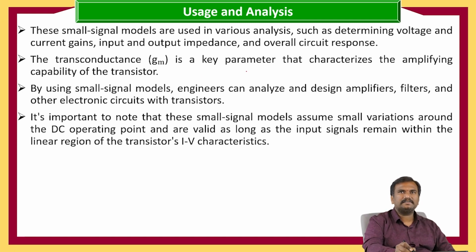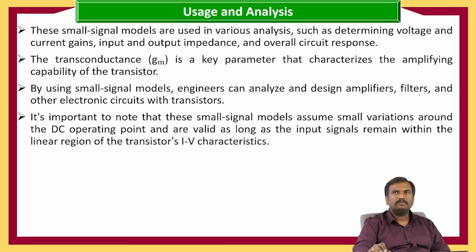The transconductance is the key parameter that characterizes the amplifying capability of the transistor. And by using the small signal models, engineers can analyze and design amplifiers, filters and other electronic circuits with transistors. When we have a small signal model, we can easily analyze and design different electronic circuits.